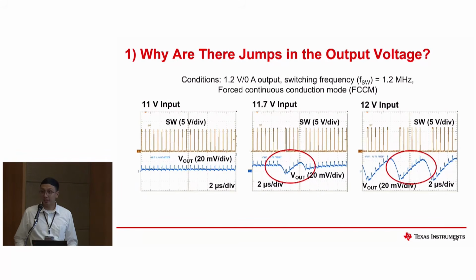The output capacitor? That can also possibly cause it, but for this case, it's not. Good guess. Anyone else? Yes, it's skipping the pulse, right? So what do you think is causing this? Load current? But for this one, it just stays at 0 amps, so there's no load being put on the output. Okay, good guesses.